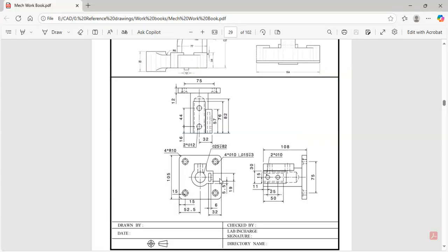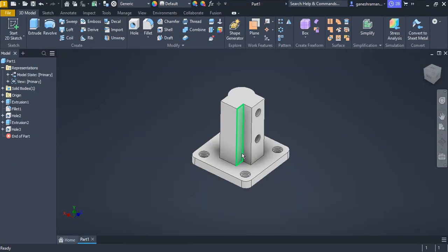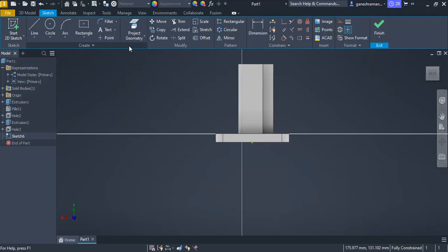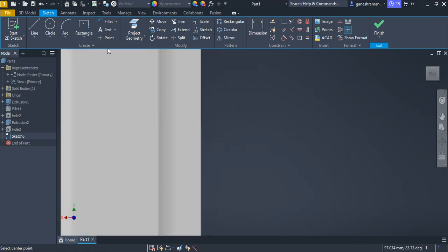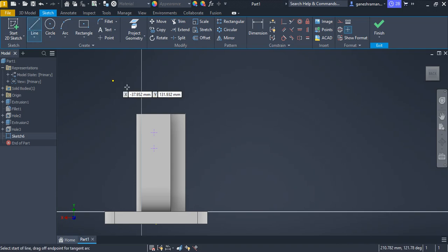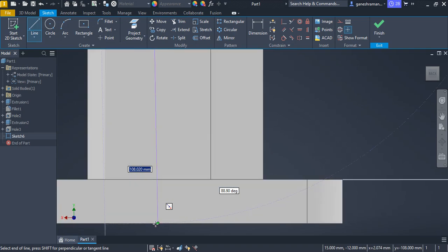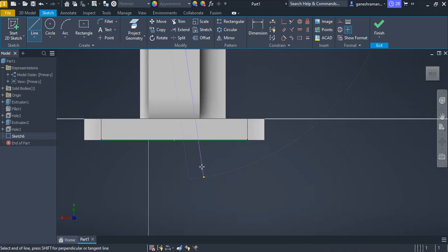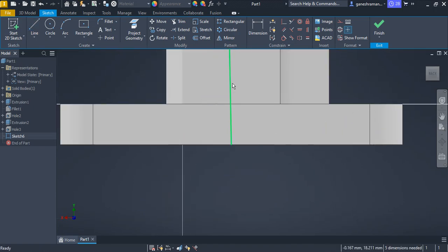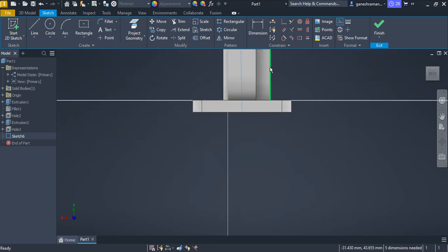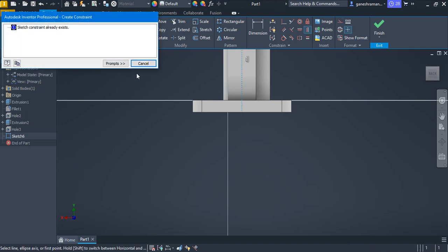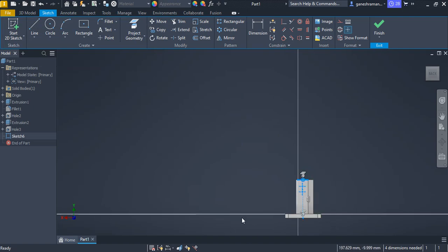Now next, this side also has 2 holes, so set this face, sketch, add 2 points like this, and use the line command from this midpoint to this midpoint. I'm not highlighting the midpoint. Select this construction and make sure this is a vertical line, which is not possible, so just delete it.